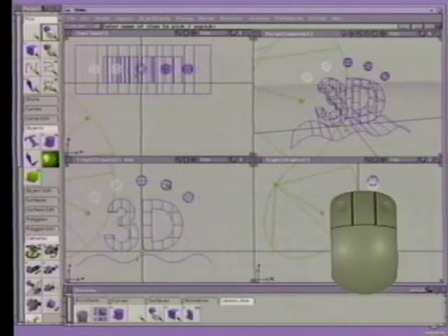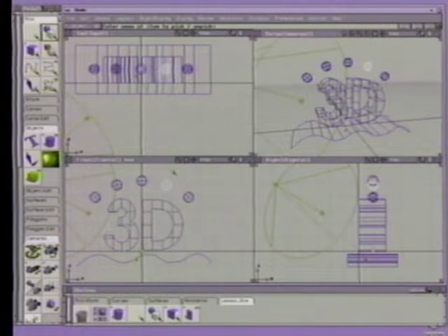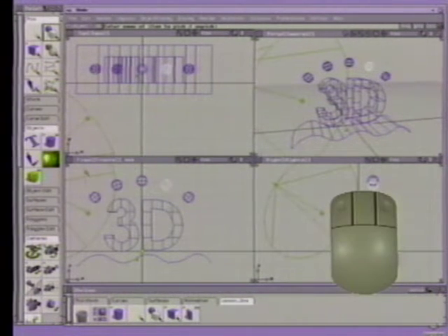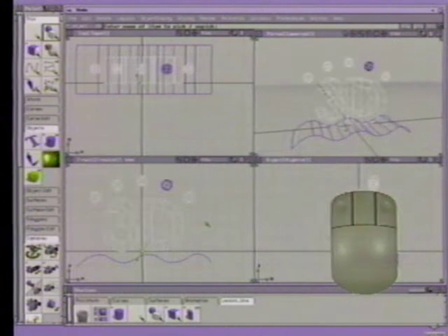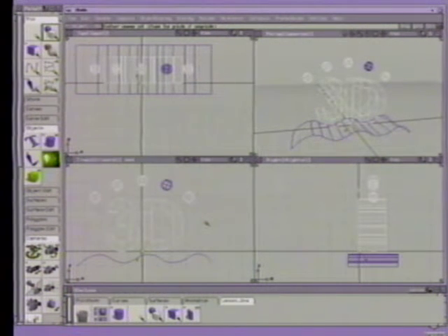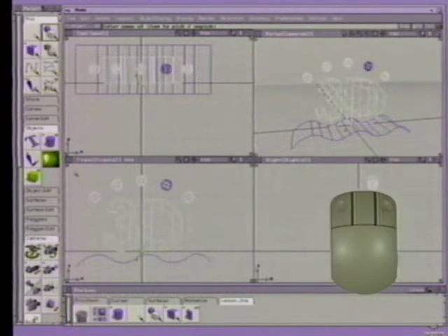Now, click on a different sphere with the middle mouse button. Now the new sphere is picked and all the other objects are unpicked. The middle mouse button lets you replace a selection with a new selection. Next, click-drag with the left mouse button to create a pick box around the 5 spheres and the 3D text. The picked sphere is unpicked while the other objects are picked.